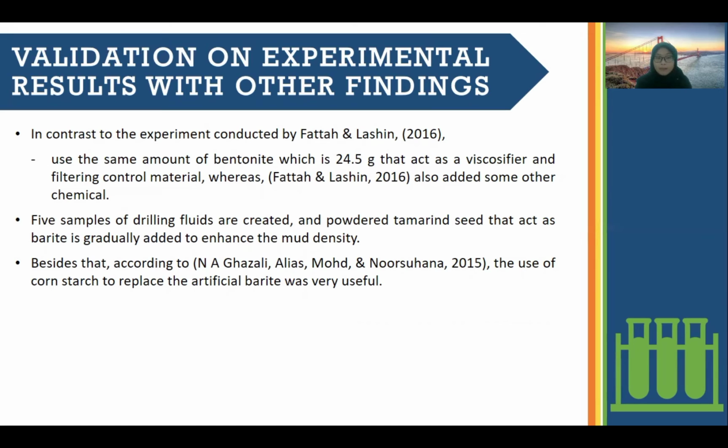Next, 5 samples of drilling fluid were created in this lab, and the powdered tamarind seed that we added to act as barite is gradually increased to enhance the mud density.